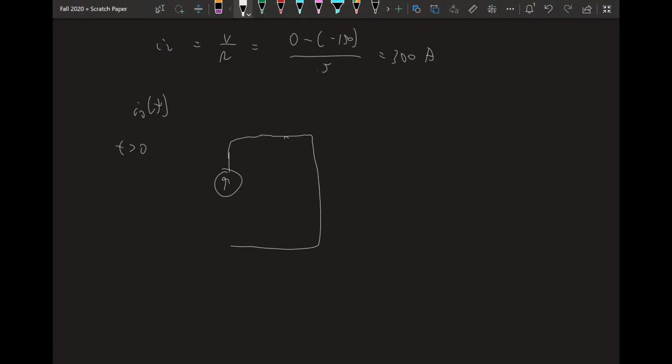When the switch closes, now we have an open circuit. We have a short circuit here. We have a capacitor here, and a resistor here. Okay. So all the current from the 5 amp current source is flowing into here. The current source does not interact with any of these capacitors, right? In fact, these capacitors don't even interact with each other. Their currents flow over here, but because of the shorts, no cross currents flow. So we can treat each of these branches as a separate natural response.